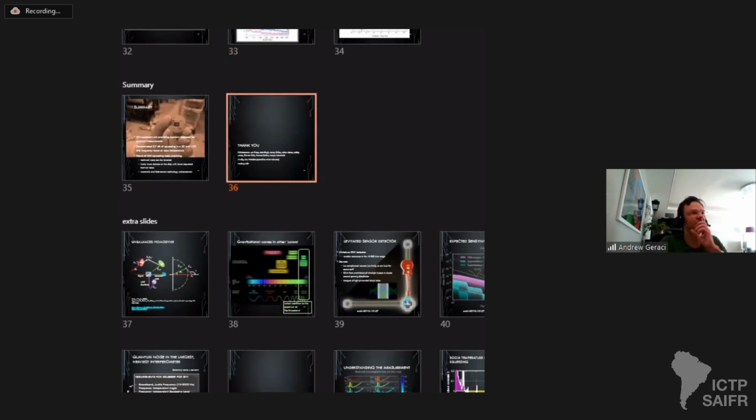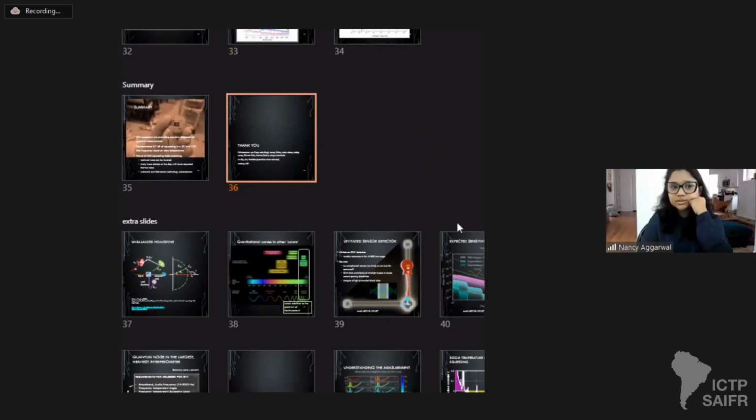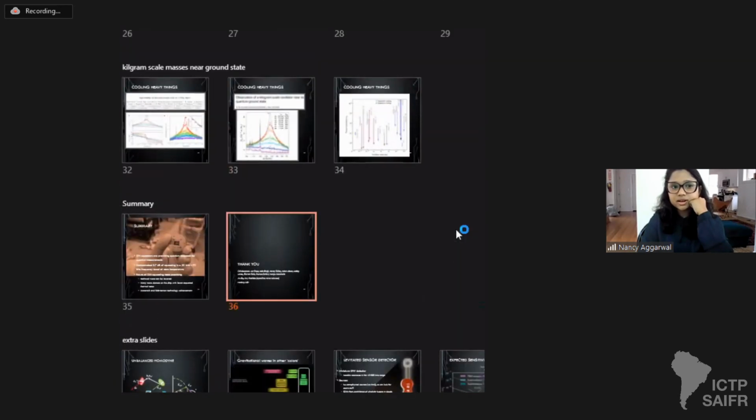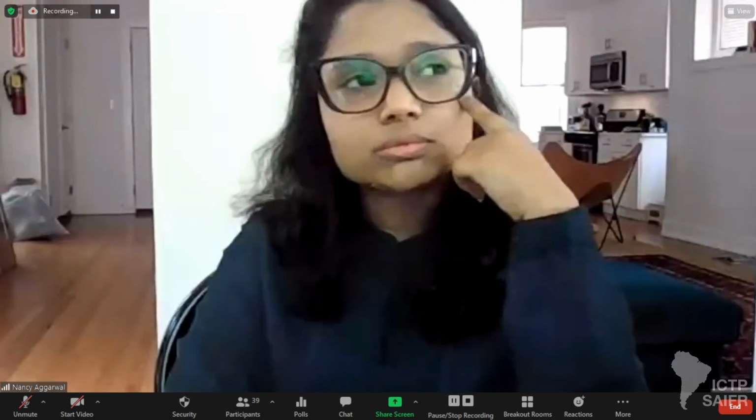I'm trying to see if I included that in my extra slides, and I did not, so I'll just answer it verbally. You're saying 10 kilohertz? 10 kilohertz is fine even with this generation of chips because we're limited by our homodyne being outside the vacuum chamber. So we have some extra phase noise, the relative phase noise between the LO and the squeeze beam. If the homodyne was moved inside the vacuum chamber, 10 kilohertz would not be a problem.